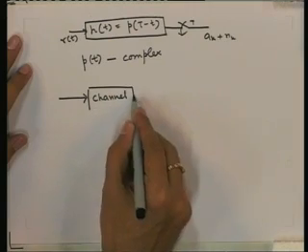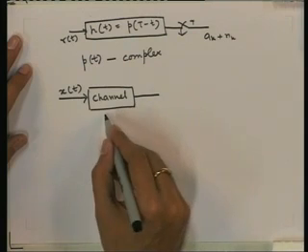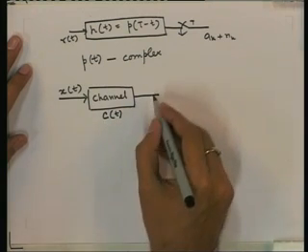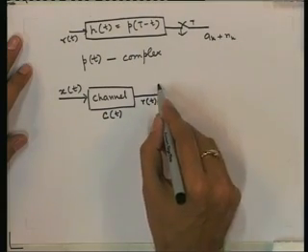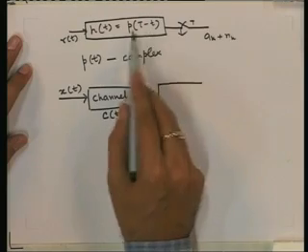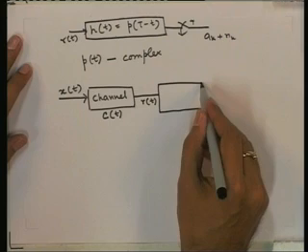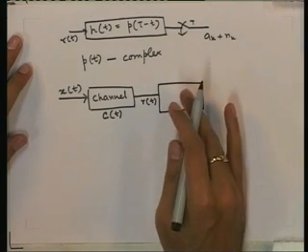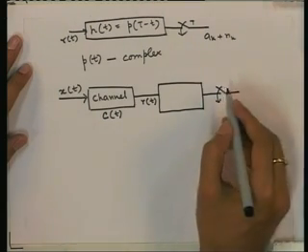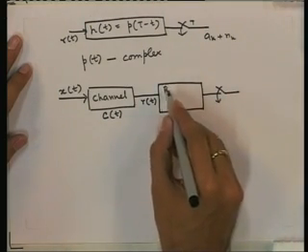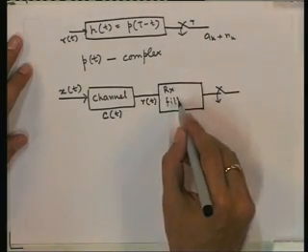This is the block diagram of what is happening. We are transmitting here, this is xt. The impulse response of the channel will be assumed to be Ct, and the received signal will be assumed to be Rt. Then we will pass it through a filter and sample at T. We will take one filter and sampler, and we will see whether this can be done for an arbitrary pulse shape, and if it can, what kind of filter we should take. This filter is called the receiver filter or receive filter,